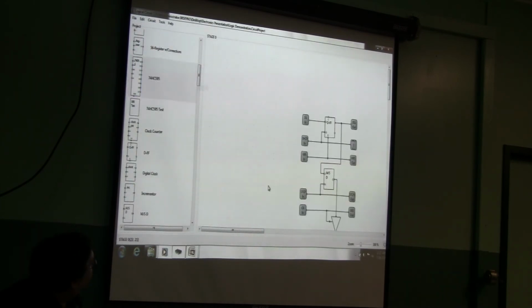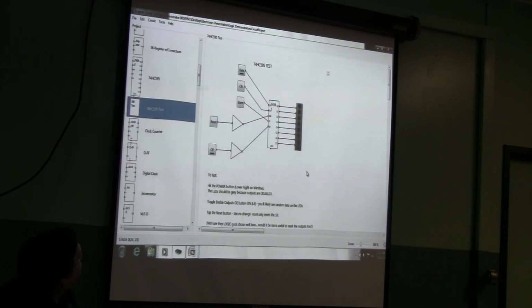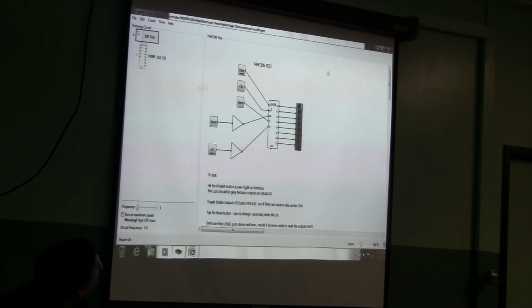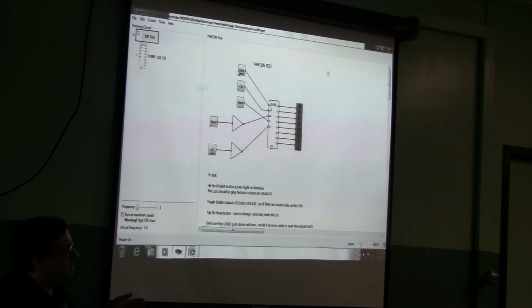Each one of these has a circuit that latches the data bit and then ripples it down to the next data bit. How that would work is, let's say I want the number 10101010, but I've only got a few pins coming out of my Arduino or my vintage computer, my Commodore, or something like that. Every clock advances to the next bit. So let's say I have 1 clock, 0 clock, 1 clock, 0 clock, 1 clock, 0 clock.